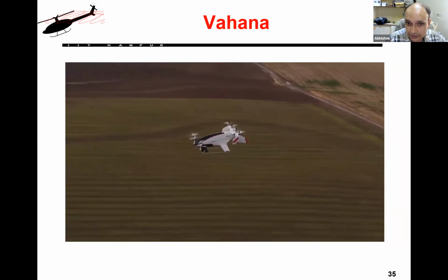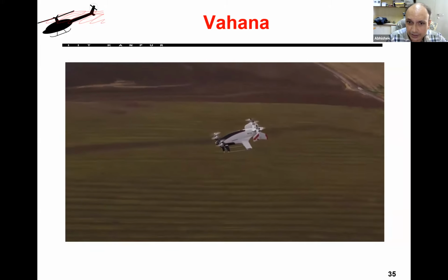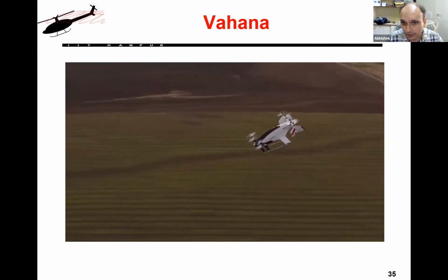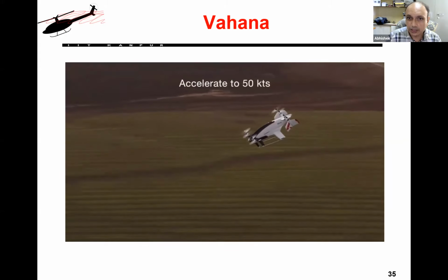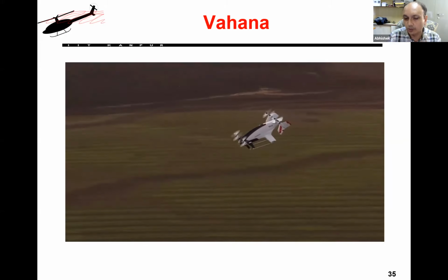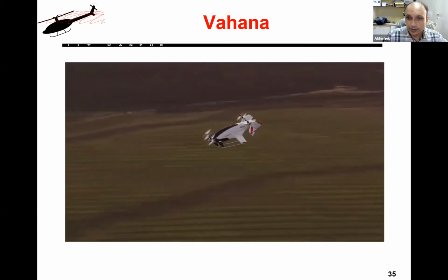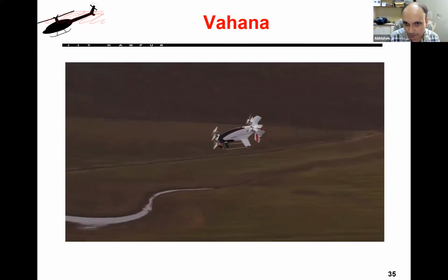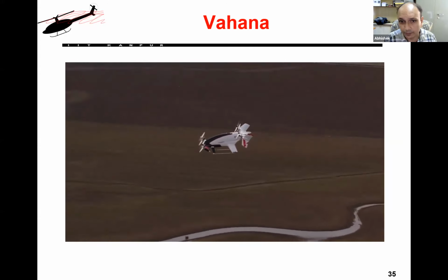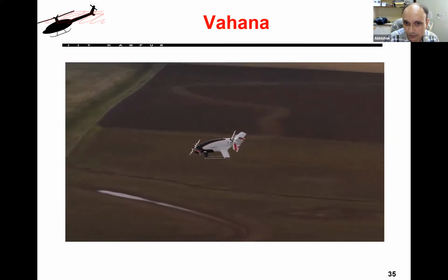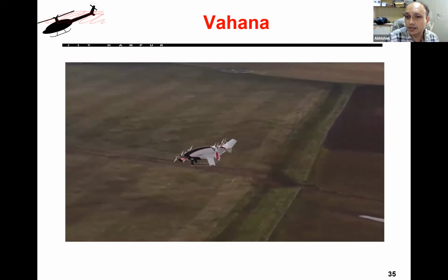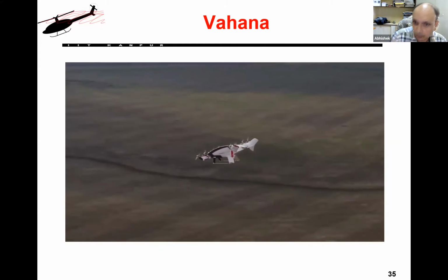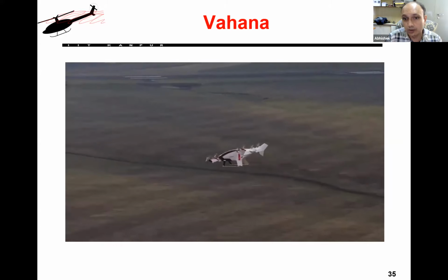So you can now imagine, in a conventional aerial vehicle, a pilot actually controls ailerons, which are moved in a particular manner, elevator in another manner. So he can manually control all these things because there are only a finite number of these, and he has 2 hands, 2 legs. So with that, he can easily manipulate 3 sets of controls. But now here, you have so many different inputs, it is impossible for him to control it on his own. But the good part is that this vehicle doesn't require a pilot. It's autonomous and it is flown through an autopilot which is on board. An autopilot can actually handle all this.